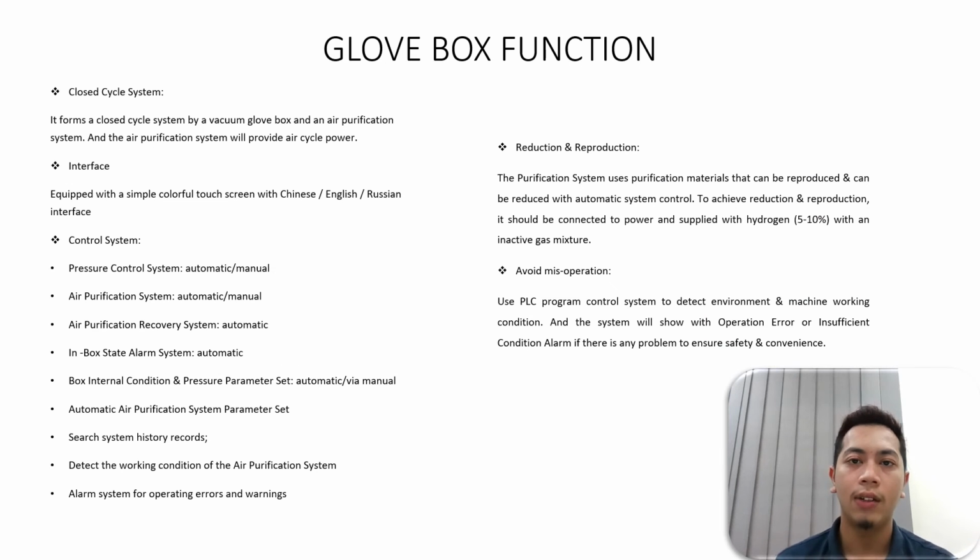This is about the glove box function. Number one, closed circle system. It forms a closed circle system by a vacuum glove box and an air purification system. And the air purification system will provide an air circle power.